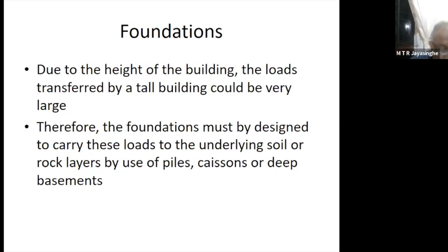It used to be about 18,000 rupees. It has gone up by about 4,000 rupees, 5,000 rupees. And when you compare that, even if you have to use 4,000 rupees more per meter cube, if you are going to get a much higher load carrying capacity, it's worth considering. It's worth considering going for a high strength pile.